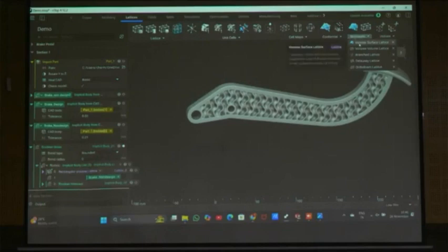On the surface also we can apply it. Whenever we say texture, it will be applied to surface bodies only. That is not applied to the 3D body. Surface lattice means we can apply the texture. Volume lattice means we can apply to the entire body. Voronoi means random points will be applied there. There is no uniformity actually. That we call a Voronoi.